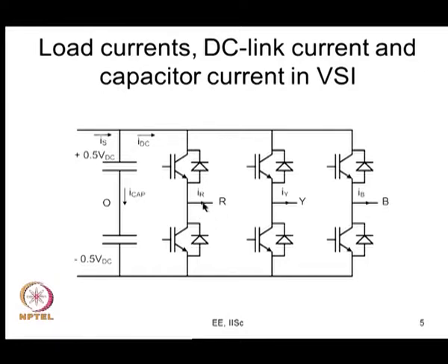As we also discussed while we were discussing voltage source inverters, we can see which device conducts. For example, you have a transistor and an anti-parallel diode in the top. You also have a transistor and an anti-parallel diode at the bottom. So, the question is who will conduct when. Let us say this is the direction of current flowing here, that is from my left to right as shown by the arrow mark here. In that case, if the top device has been switched on, the bottom device will be switched off, and the top transistor will actually conduct this current.